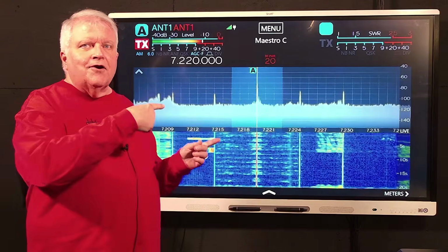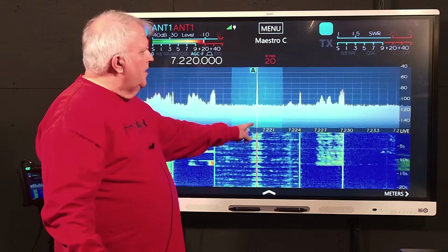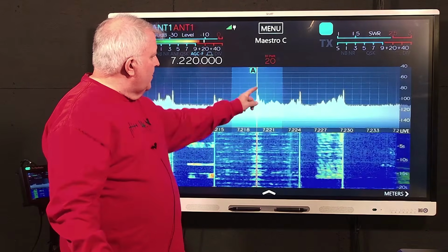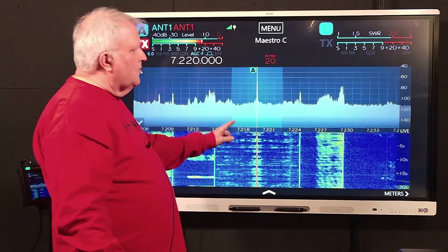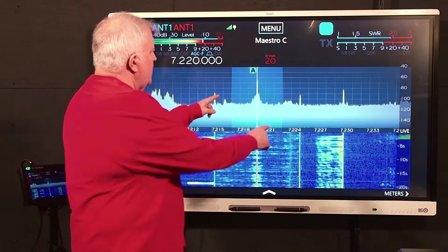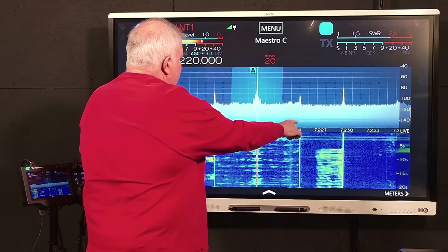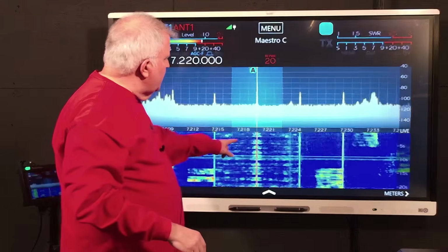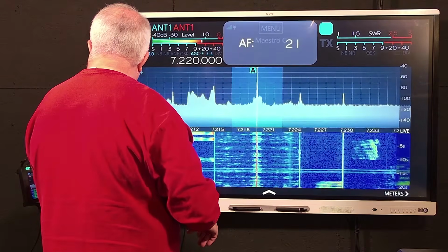And what we're looking at here is an international broadcast signal. This is the radio frequency carrier, the center part that we saw. And the sideband, the lower sideband, actually we say that for ham radio it extends 6 kilohertz wide. That's what this is demarking. But for international broadcasts, they can actually go plus or minus 5 kilohertz, so it's 10 kilohertz wide. This is an international broadcast station. I'll tune up the audio here just to see if we can hear it.